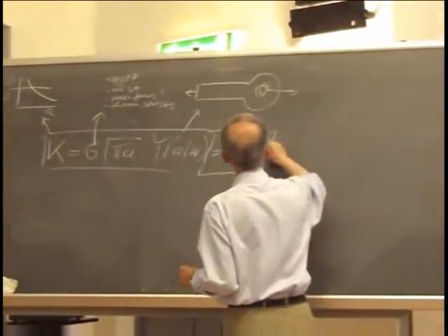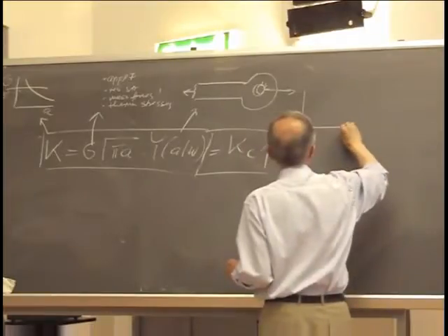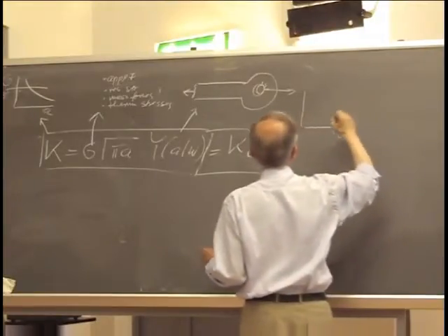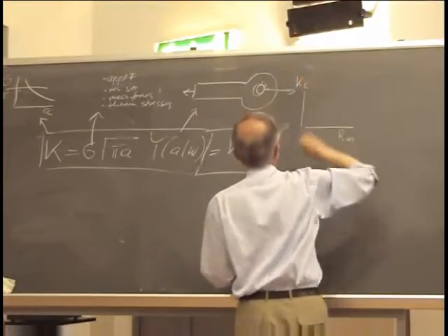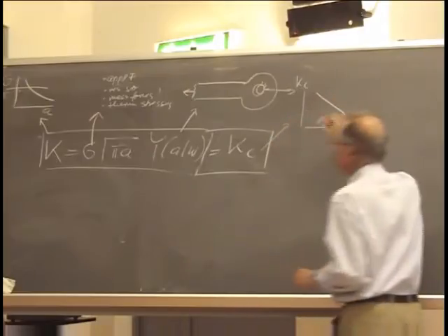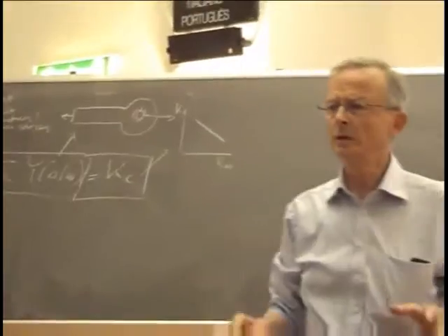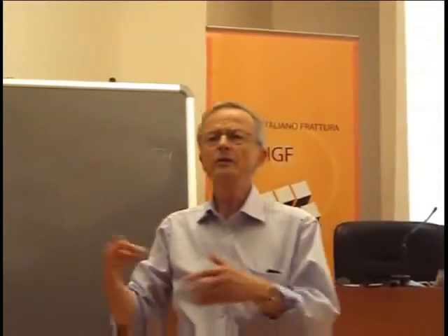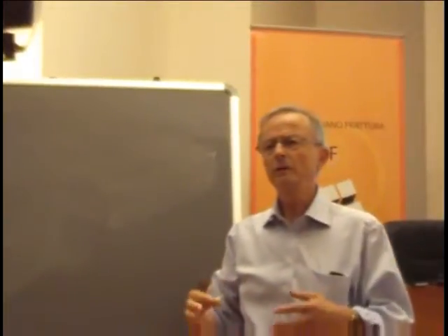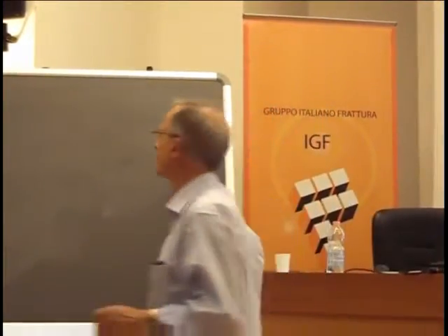Kc or K1c, whatever. If you have a material with variable yield strength or maximum tensile strength, and here we plot the critical K value, we get this relationship. The harder the material, the lower the toughness normally, you know. You can increase the toughness by adding alloy elements, but then you have a different material. You have high strength and high toughness, but you have to pay for it, like I said several times, in terms of more expensive material.